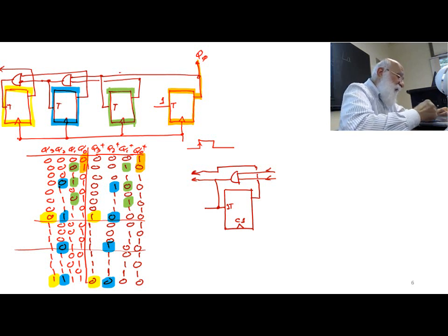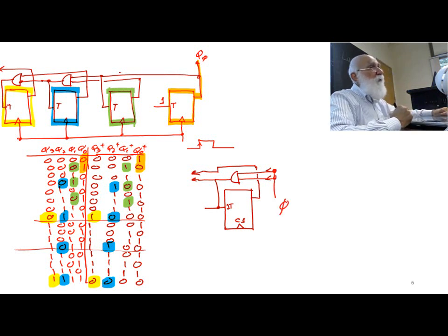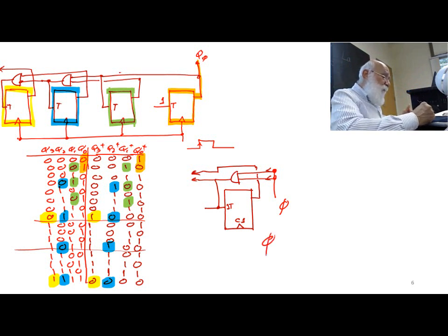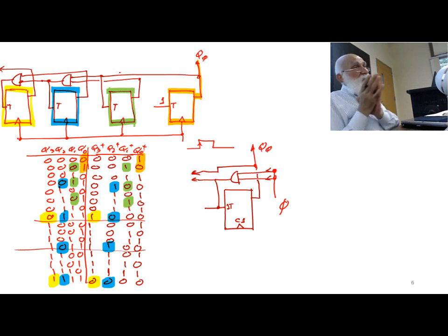Okay, but that doesn't really matter, because for the rightmost flip-flop, if I do have that AND gate, then if I tie these 2 inputs together and put a 0, then what happens? The 0 on the AND gate of the rightmost flip-flop, this is bit number 0, Q0, propagates all the way to all the AND gates.